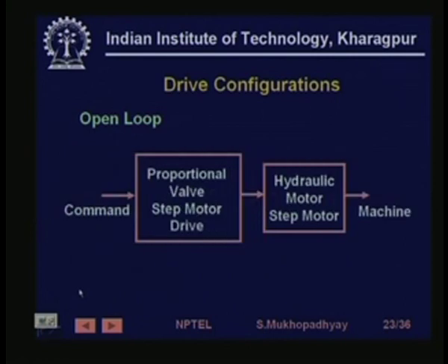Typically, the drives that are used are sometimes open loop, especially when they have switched, let's say low power drives like stepper motor drives, which are cheap because their drive electronics is much simpler. So sometimes we have used this kind of drives which are open loop and use very simple drive electronics.